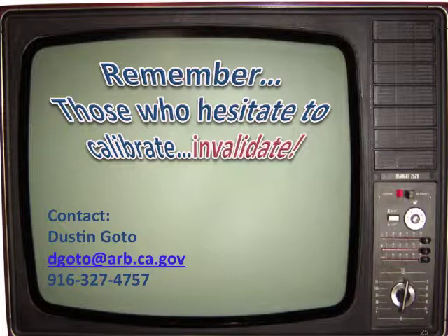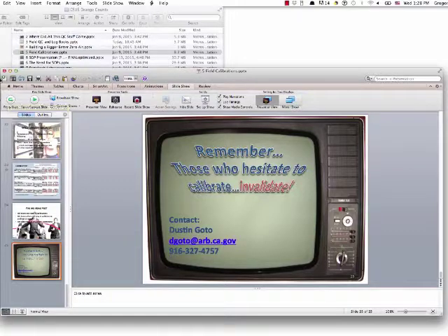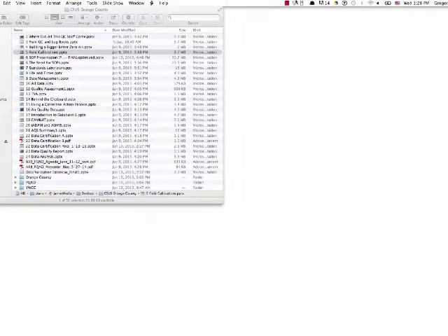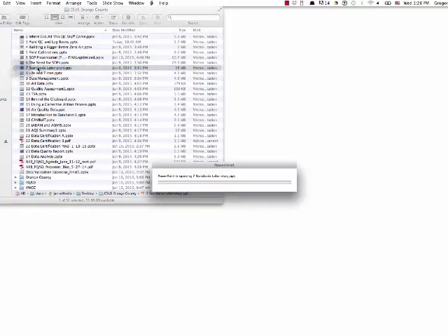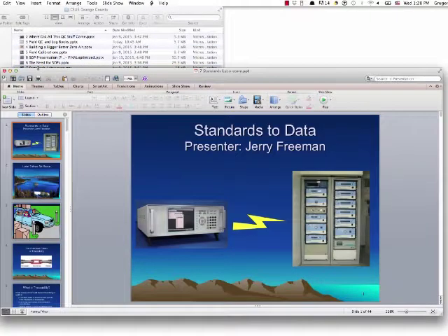Yeah, recently, I'd say in the last year, we've been getting a new kind of tape, I guess from Met One. And it's in a thinner box, and the tape is harder. It's more polished, and it doesn't shed like the old tape used to, but the downside is we have higher zeros. At least I've seen that, and I've talked to other people. They've seen that too. And I consistently get about 0.4 for my leak checks, and the gate's clean and everything else. I think it's a factor in the tape. Okay.